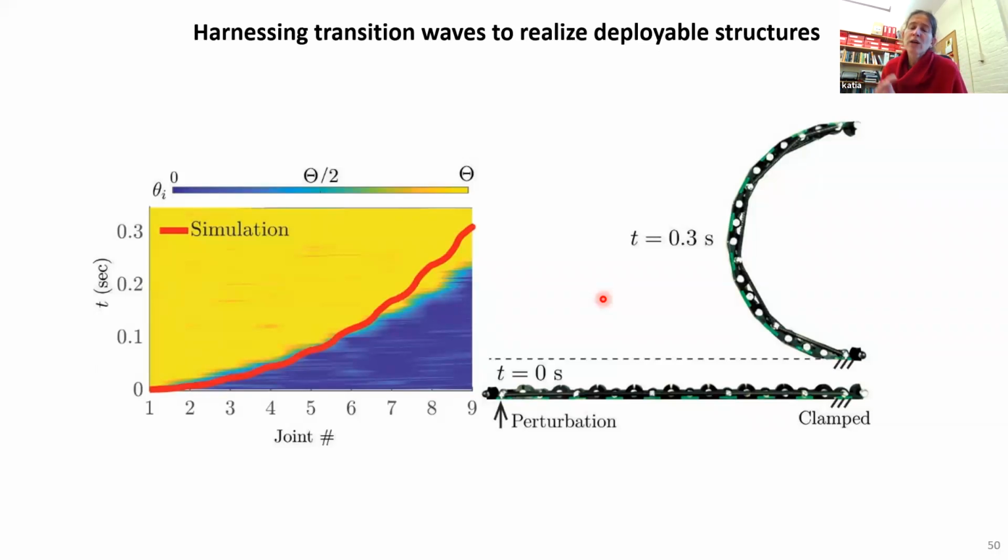Okay. There are all sorts of games you can play. All the angles are the same, it's homogeneous, all linkages are the same. The target was 20, but I would say it's oscillating by about plus or minus 4 degrees, because of the way we laser cut and then manually assemble. So there are imperfections coming in, but there are all sorts of games you can think of playing, because you can intentionally vary, for example, the angle theta.